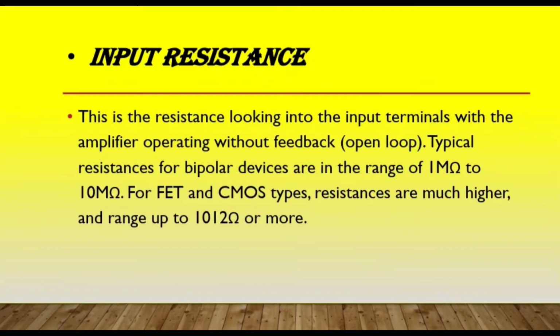Input resistance. This is the resistance looking into the input terminals with the amplifier operating without feedback, open loop. Typical resistances for bipolar devices are in the range of 1 megaohm to 10 megaohms. For FET and CMOS types, resistance is much higher, up to 10^12 ohms or more.